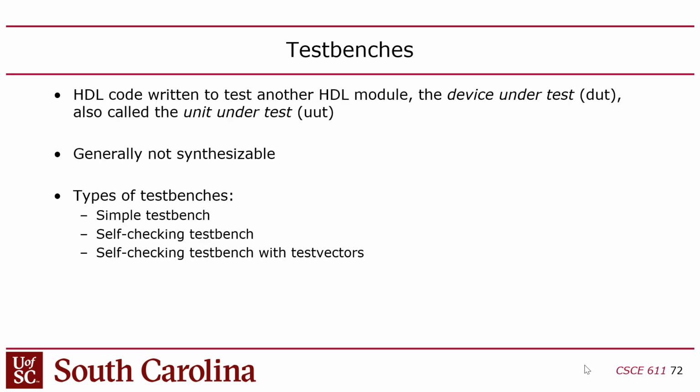Okay, this slide just says what I just said. Okay, so now let's talk about test benches. I showed you, I think I did a demo last Monday where I used QuestaSim to simulate a design, and I used force statements in QuestaSim to set the inputs, and then I visually observed the corresponding output, right? But that's a really bad way to test. I mean, it's good for testing little things and doing debugging, but it's not a great approach for testing overall, right? Because you don't want to have to just stare at a waveform to figure out if your design is working. A better way to do it is with a test bench.